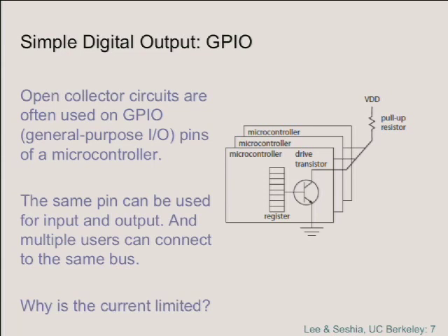An arbiter, which is a piece of hardware hanging off the bus, notices that somebody pulled this down low, or maybe more than one person did, okay? And it attempts to figure out which one did. Okay, so there's some sort of handshake protocol that happens.